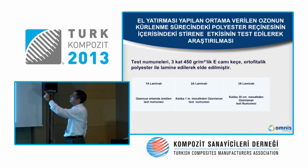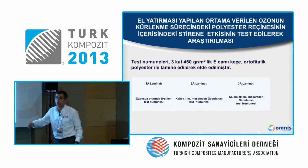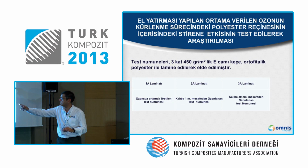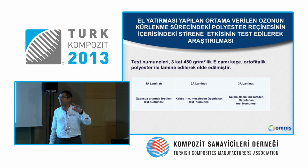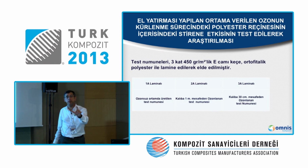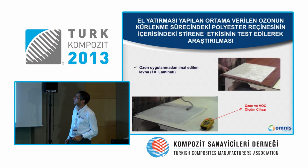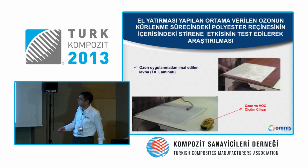We have made some tests. We have put 3 coatings of 450 grams per square meter of E-glass and orthophthalic polyester and laminated it. A 1A laminated product has been produced in an area in the premises where there's no ozone. In 2A laminate, we have put the ozone on the mold, and on 3A we have given the ozone on the product from 30 centimeters away.